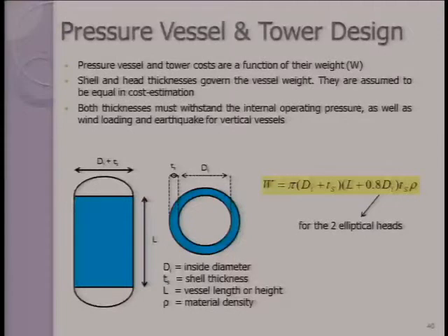From this equation, we know the inner diameter because this is something that you choose depending on the flow rate of your fluid. For example, for the distillation column, the selection of the inner diameter will depend on the vapor flow rate. Basically you want to prevent flooding or liquid weeping in the trays.